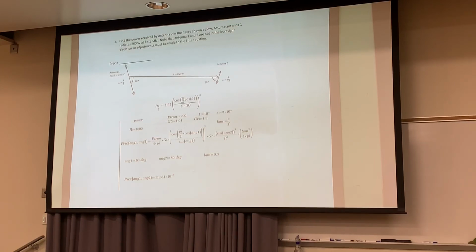Remember, a waveguide, the way you think of it is, the wave has to fit in the guide such that it at least has a null to null. So think of a sine wave, all right? A half wavelength has to fit in that guide over the long dimension. If it doesn't, it doesn't fit in the guide and it becomes an evanescent mode and it just shorts right out.